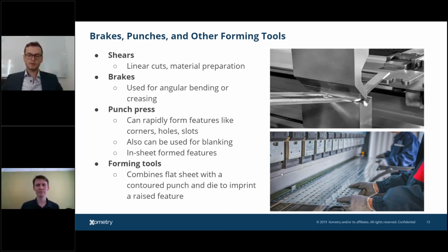And in general, unless you work in or run a fabrication facility, your flat pattern is going to be wrong, right? That's the long and short of it. I wish that SolidWorks or Inventor was smart and said, hey, I know exactly how to unfold this and it's going to be accurate. But if you want ±5 or ±10 bend to bend, you're probably not going to get it with your automatic unfold.